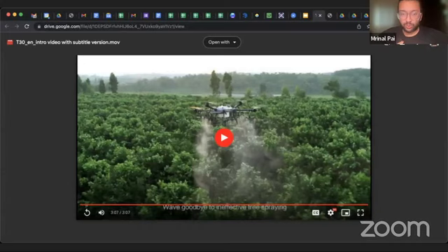It is equivalent to a two-wheeler or a four-wheeler vehicle today, where you buy a drone, you register it once, you get a registration number, and the operator needs to have not a license like a driver license, but a training certificate. He needs to be a trained operator to operate these drones, and the drone needs to be registered, and you can operate this freely up to a height of 400 feet. In the agriculture spraying case, you don't need to fly that high. You're flying maybe a meter or 2 meters above the crop canopy. And you can freely fly up to such height in green zones.